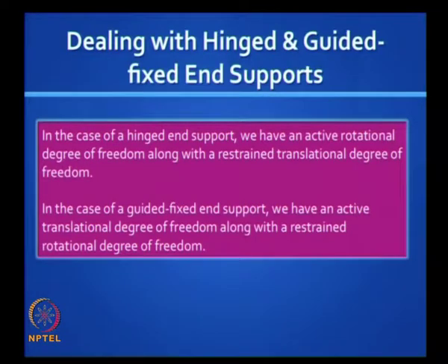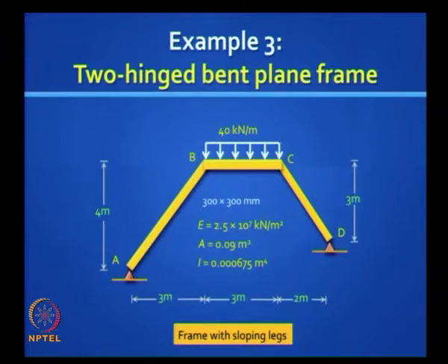Dealing with hinged and guided fixed supports is exactly similar to what we did for beams. You have to release some degrees of freedom. So let us take another frame problem. This is a bent frame. Remember we did this frame earlier by the slope deflection and moment distribution method, but here you will get slightly different answers.